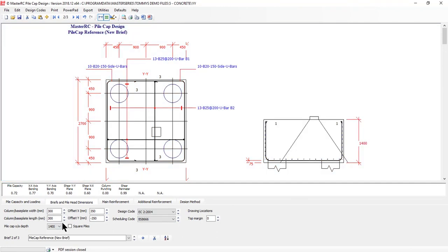As you can see, it goes up very, very quickly, because as you get your thicker pile cap, your perimeters have been pushed out, which makes them longer and obviously deeper at the same time, so you're getting a squared function on that increase in capacity.